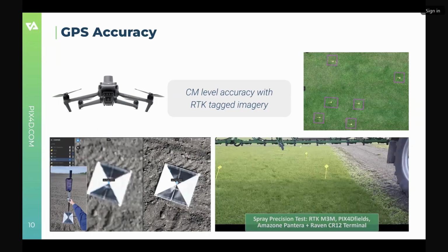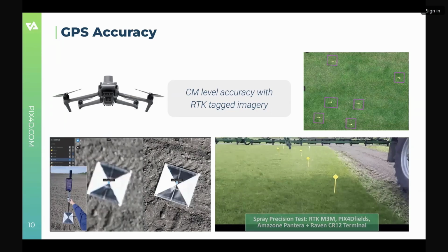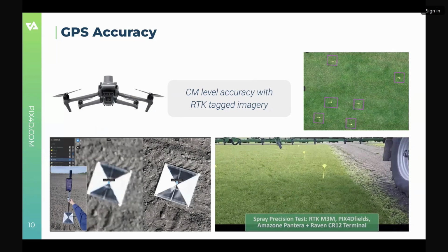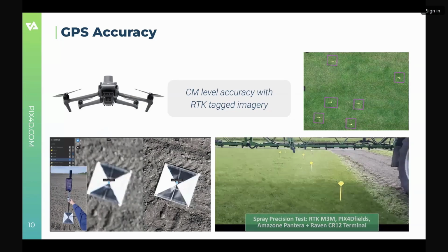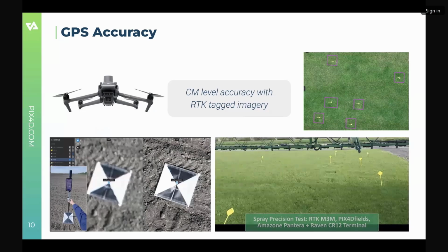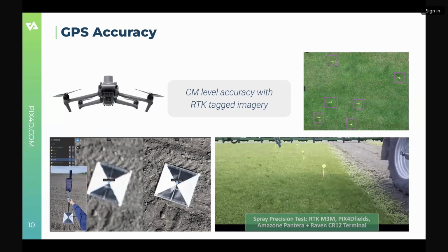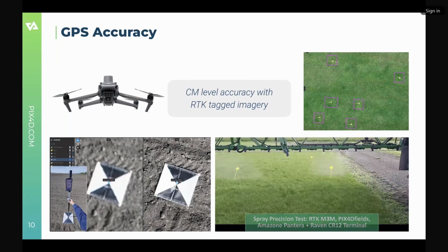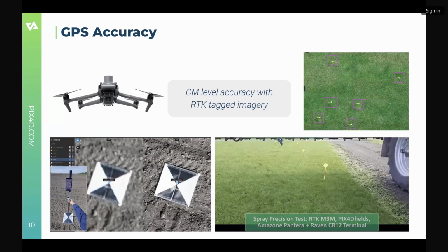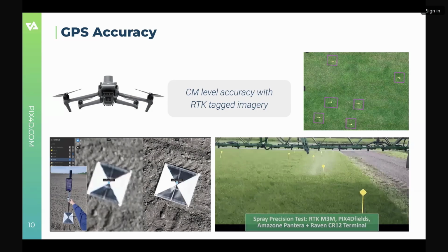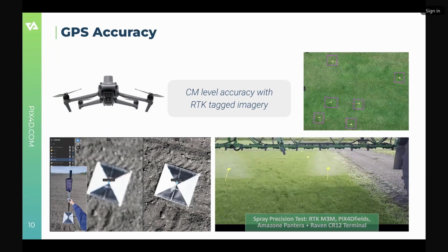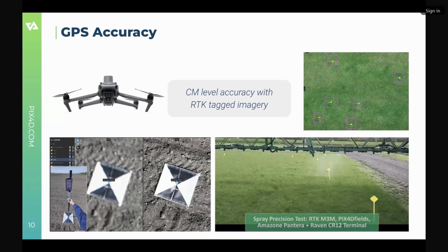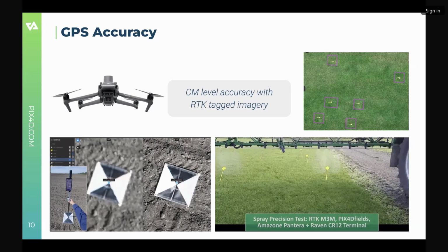Well, yeah, the answer to all problems is high tension power lines, or power lines in general, right? That's what we're trying to avoid, and that's really the number one reason for problems here. But if we're mixing accuracies, whether it's RTK and then GPS, or we're using two different base stations in two different areas with completely different datums or survey coordinates, what could possibly happen to our drone? Yeah, we could have misalignment, even an offset, and so that one power line we thought was here is now here, and our spray drone is flying right into that power line, right? So we want to use the same source if we're going to do this.